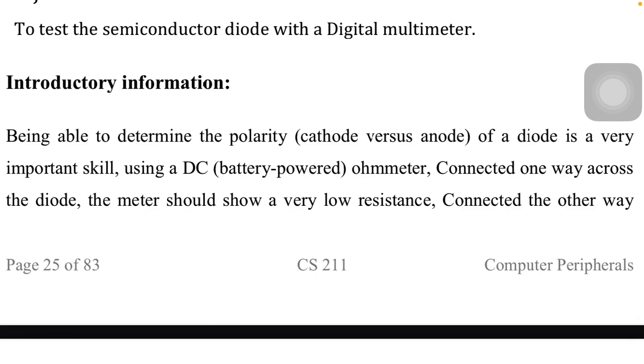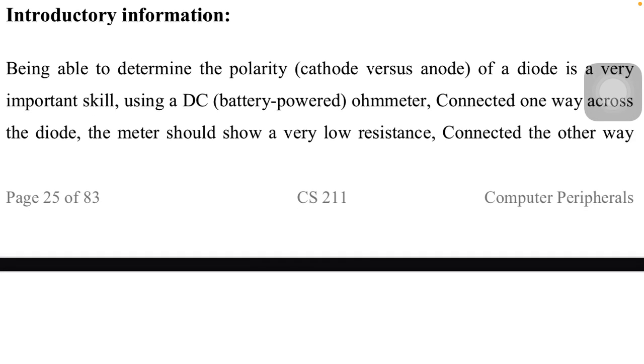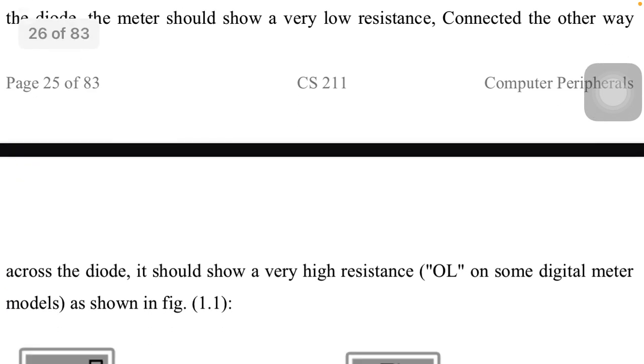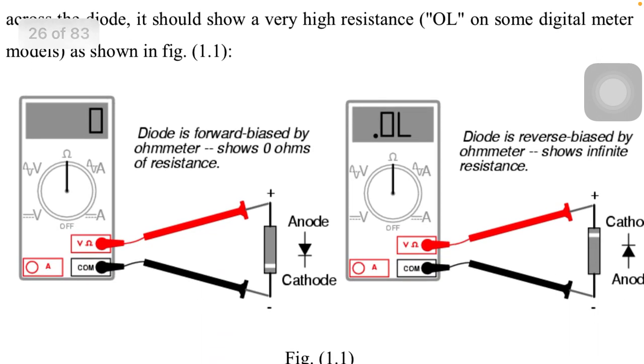Like a diode, it will not conduct if the voltage is lower than 0.7 volts. To block it, current will not pass until the voltage is up to 0.7 volts. It will not pass, and it will drop 0.7 volts. The excess over 0.7 volts will be passed on. Semiconductors, you need to know how to test for them.